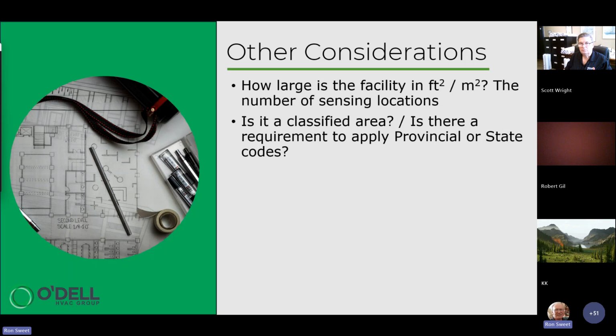Portable radios for communication, or portable wireless telecom type communicators, or handheld gas detectors or any other type of handheld device moving around in that classified area are going to be manufactured and designed such that they meet the classification of being intrinsically safe.